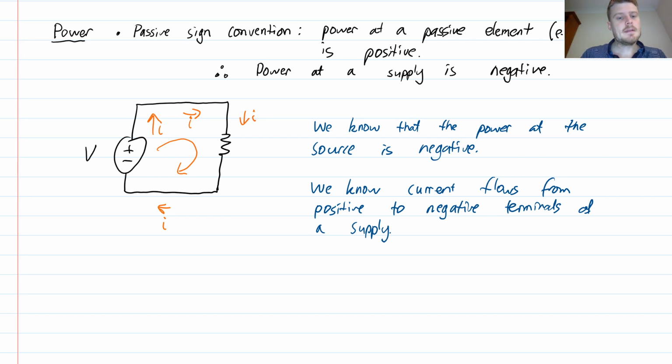And so therefore we know in this particular circuit that the numerical value of I should be positive. Here, the value of I, as I've drawn it, is positive, because that is the true direction in which the current will flow. If I had drawn the arrow the other way, it would be negative, but I know that it needs to be positive just based on the definition of conventional current.